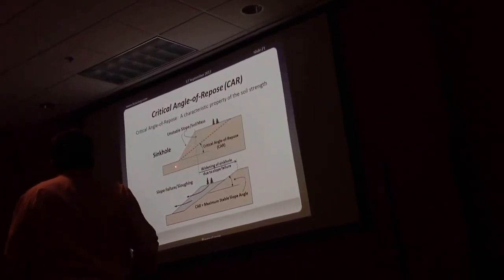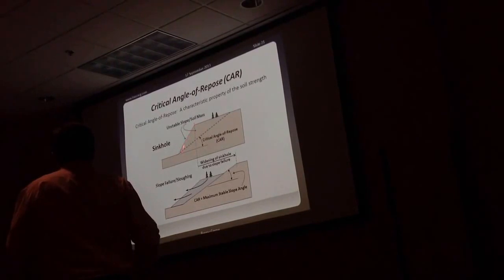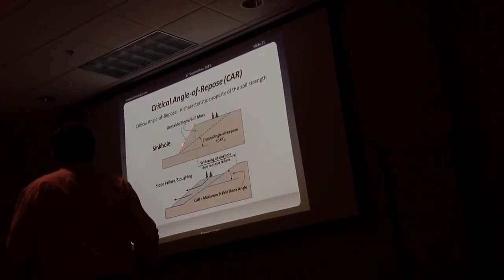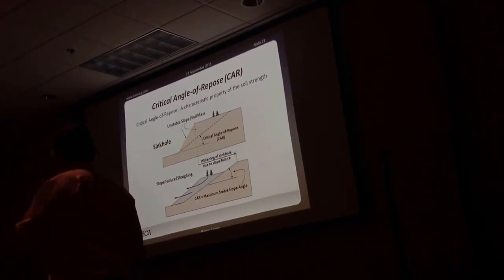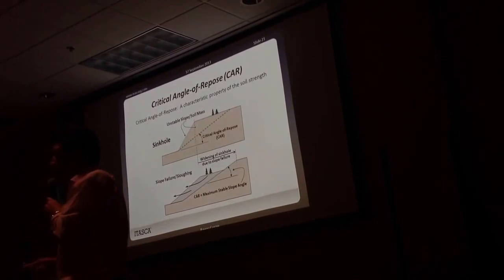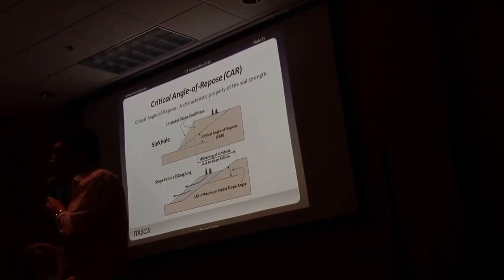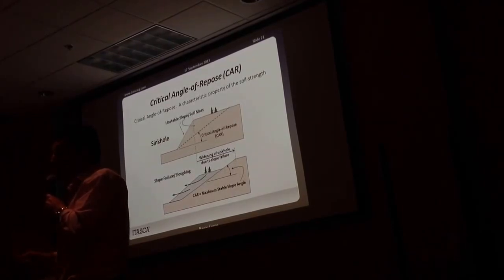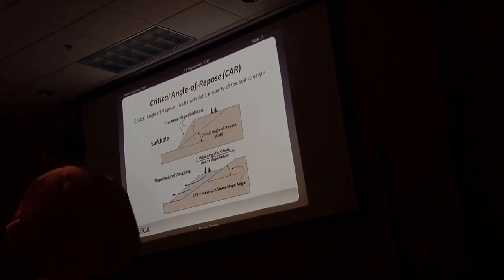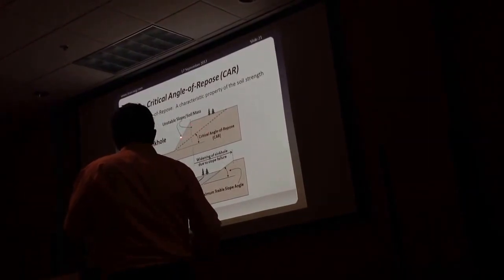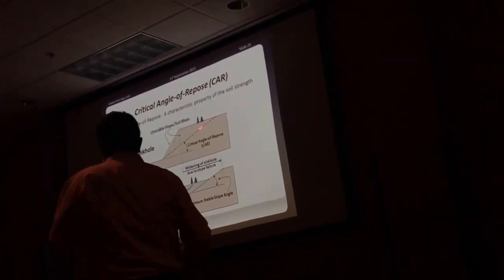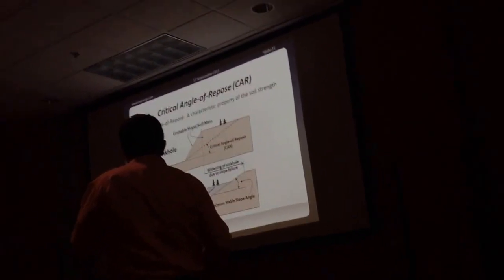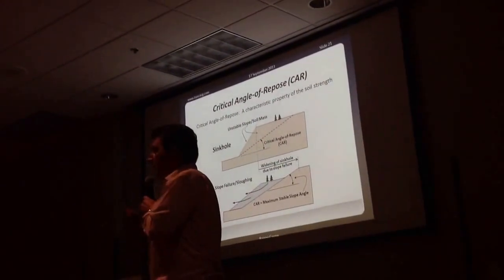So, as I say, this steep angle, depending on the material, can be quite unstable. And that's what we've seen around the sinkhole. We think that the sinkhole margins are actually critically unstable and can slide at any moment given a sufficient trigger. And what they're doing is they're working to get a much lower angle of repose to create stability.